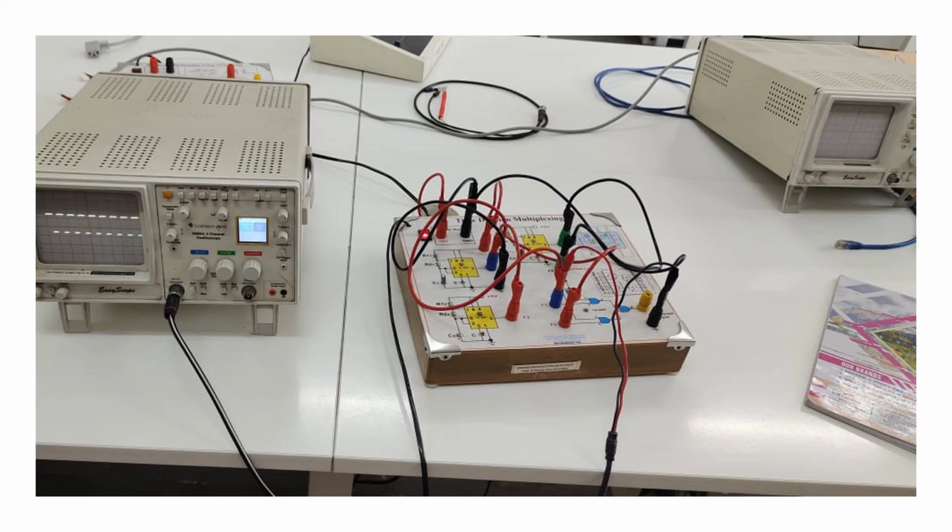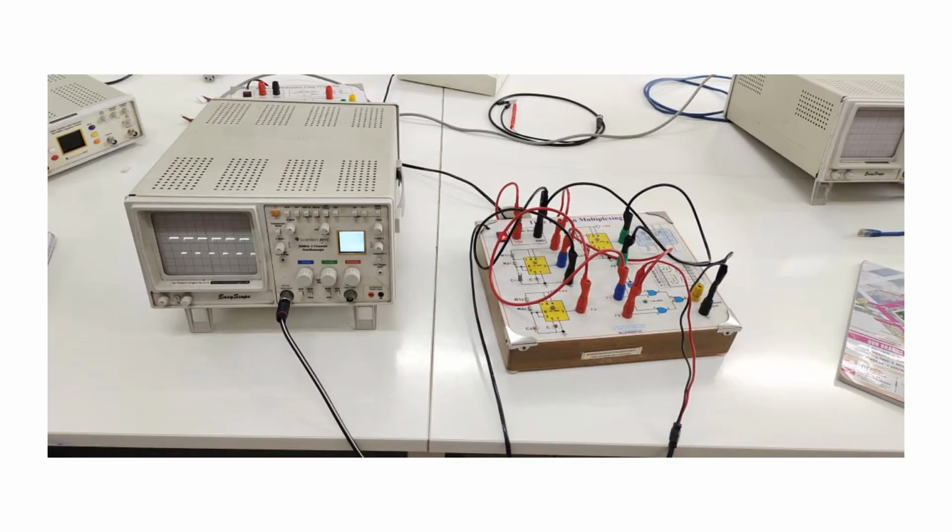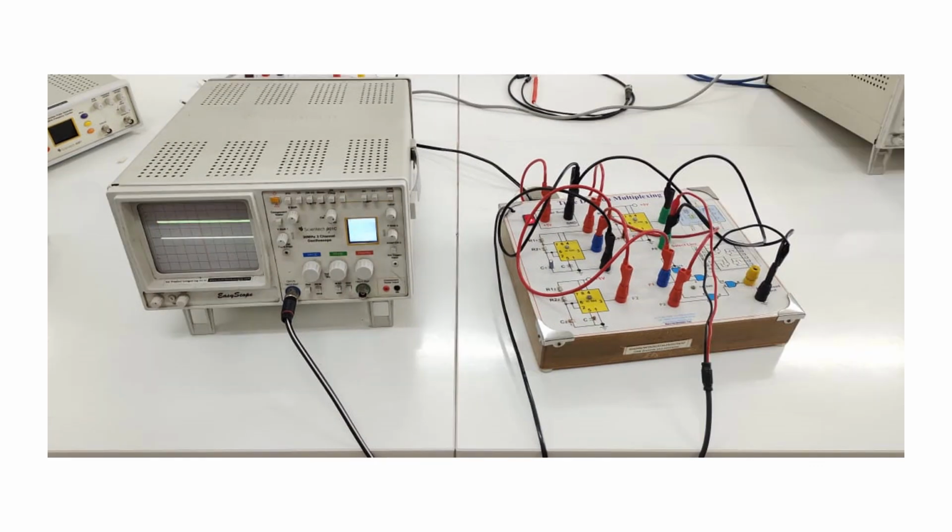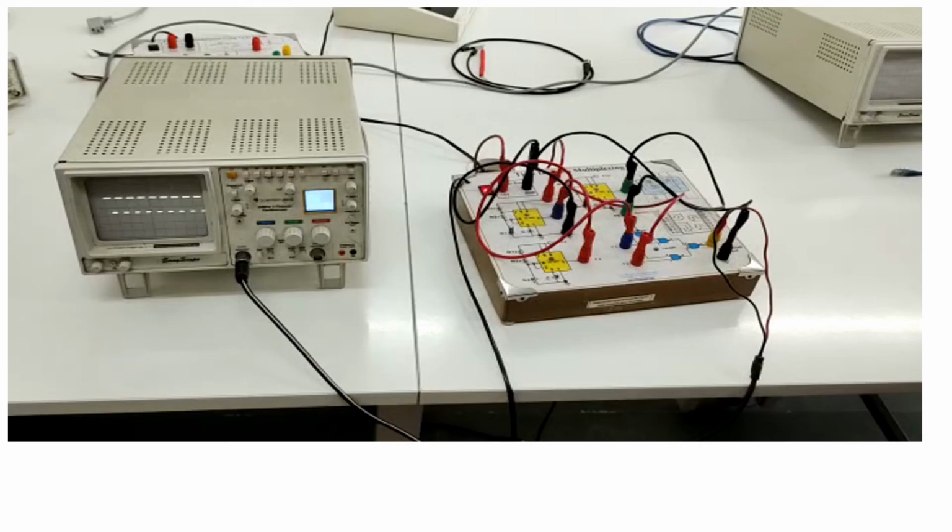Now we are connecting the CRO probe to F2. See what type of output is generated. Once we connect the CRO probe to this F2 frequency, we get this type of output. Now we are connecting the CRO probe to F0. We get the oscillatory output. Now the final response coming from this time division multiplexing, all these three outputs combined together, will form the final response like this.